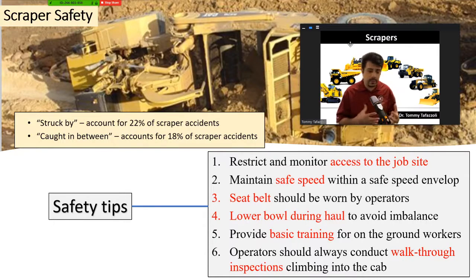You have the people, you have the machines moving behind the scraper. You need a person on the ground who can watch the surroundings of the scraper and make sure that, especially when it is backing, it is not creating a potential hazard for anyone.